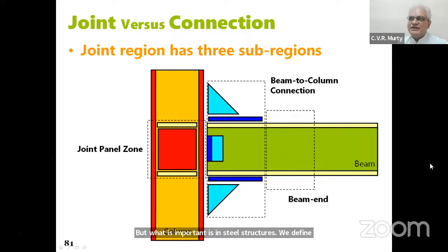And that is actually referring to the common area between beam and column, but it is a part of the column alone because the column goes through and the beam is joined to that column. And the fixtures that we use, it could be cover plates, rib plates, web angles, seat angles, cleat angles, all of that, or continuity plates, all of that will become the connection items here.